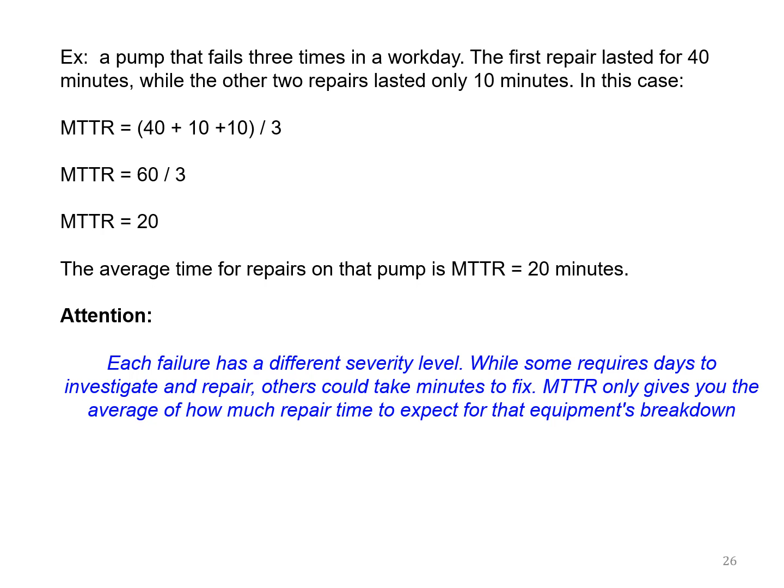MTTR can only give you the average on how much repair time to expect for that equipment, but it doesn't tell you the different severity level. If you want to know how severe a certain failure is, you need to go into more detail on the individual maintenance time for each failure.